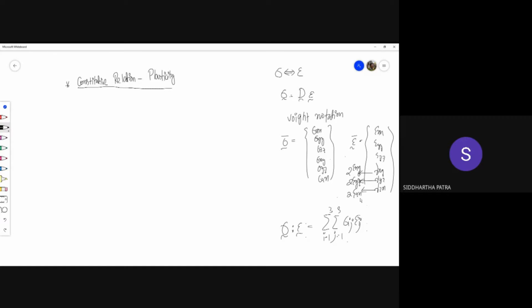Now that inner product can simply be represented with this dot product right here, which is again an inner product, but involving two vectors. Okay. Now, if I had not multiplied 2 over here, in this case, I'll be having total 6 terms. So sigma xy times epsilon xy and so on. But if I want to add sigma yx times epsilon yx, that is essentially same as sigma xy times epsilon xy, because you see the matrices are symmetric. So how can I achieve that? By simply putting a coefficient of 2.